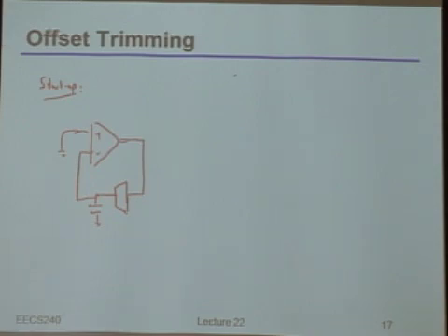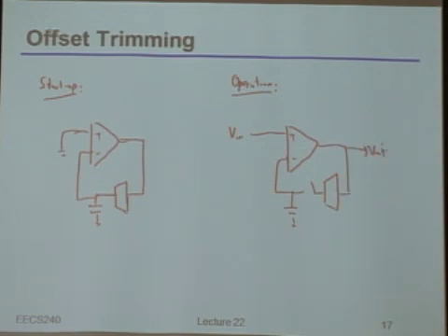So now once I've done that, during normal operation, I take the input signal, I have that connected to my amplifier, and I basically just disconnect the OTA. In other words, I store whatever signal ended up being accumulated onto that capacitor. Once I'm really operational, I just leave it there on the capacitor. And from all time forward, I'll just always be subtracting that signal out. But I can still recover these DC signals at the input. Make sense to everybody?